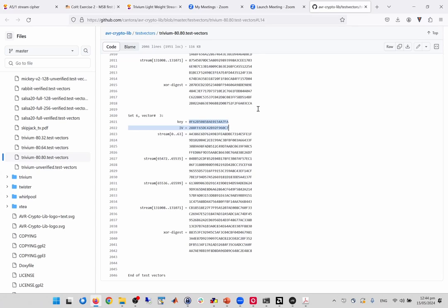And when everything works with all 0 inputs and the test vector is correct, then you test the other inputs and you see, again, it doesn't work, because now you mess up the order of the input bits and the order of the input bytes. And there you provide other test vectors, as small test vectors where only one bit is 1, for example, to find out where the problem is.